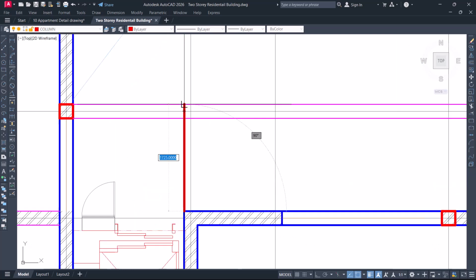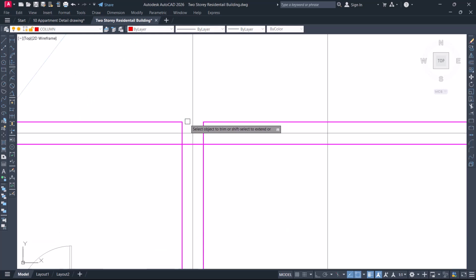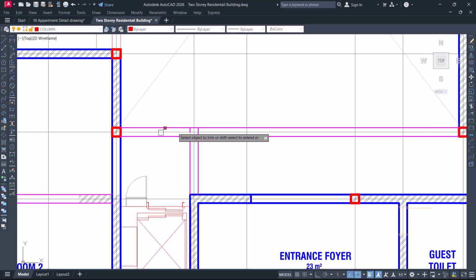All right, I will offset 225 to have the thickness of that beam. So this now becomes our cantilever beam. Now what's the cantilever beam length? Let's see. From here, grid to grid, what do we have? 1.7, which is nice. Okay, so I'll have to create this, and then let me trim this now off. Trim this off. Sorry, you enter, and then trim this off. It means that this cantilever beam now is carrying this beam at this point.